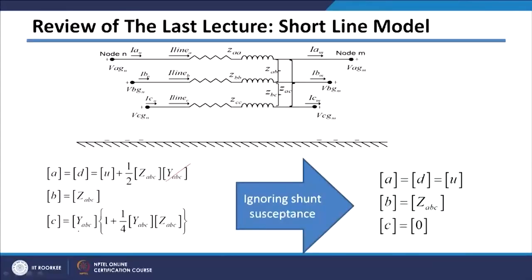And in case of the short line, we have seen that you can get the ABCD matrices by neglecting the shunt admittance. In that case, you need to make these admittances equal to 0.